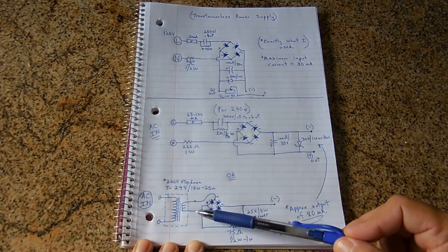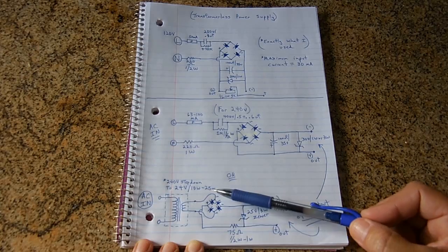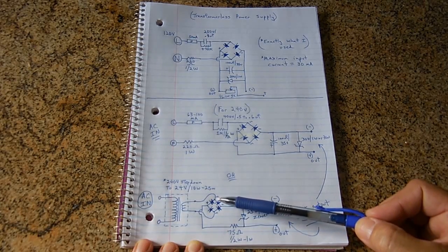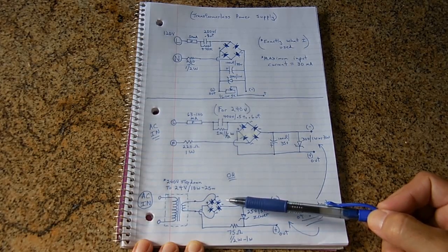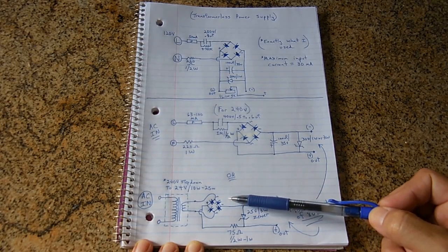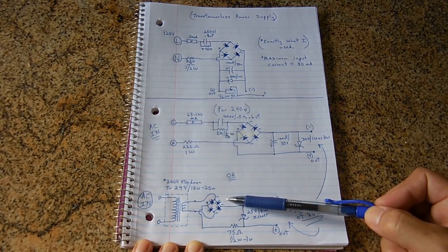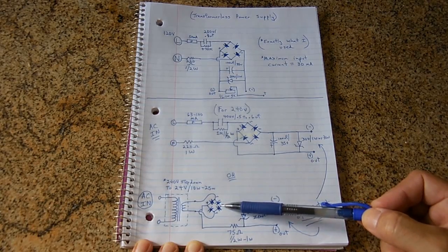So we're going to take that alternating 32 volt no load output, and that's going to be connected into a bridge rectifier as well. The bridge rectifier, if you use one that's pre-packaged, it could be extremely low in current, a 100 or 200 milliamp rating. If you find one that's 1 amp and it's really inexpensive, you could just buy the 1 amp rectifier.